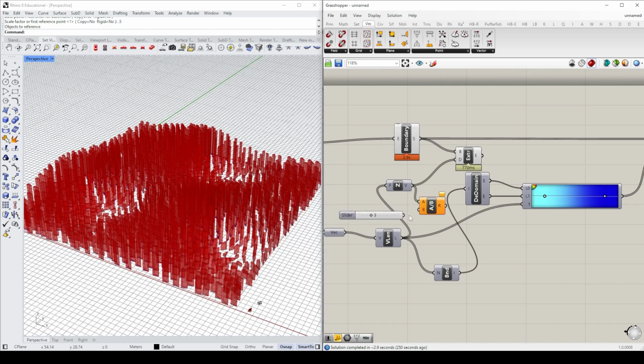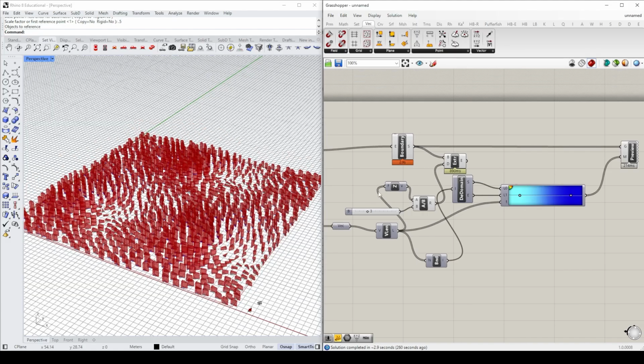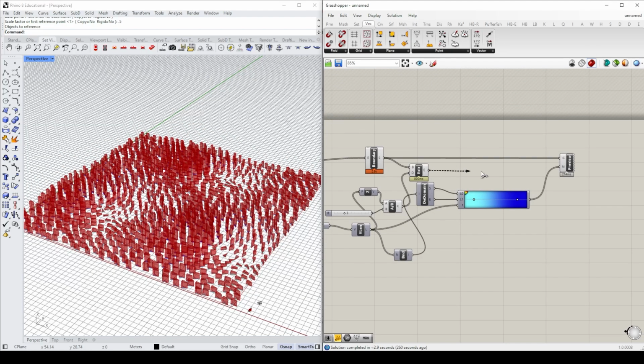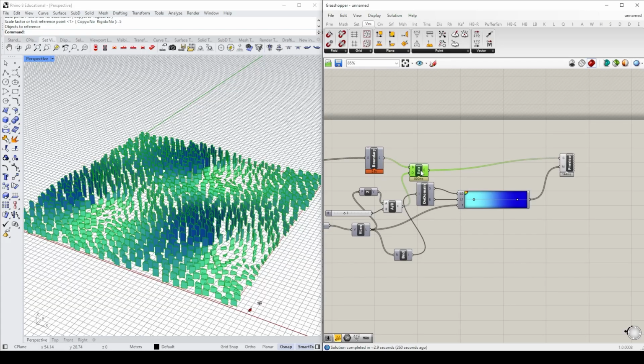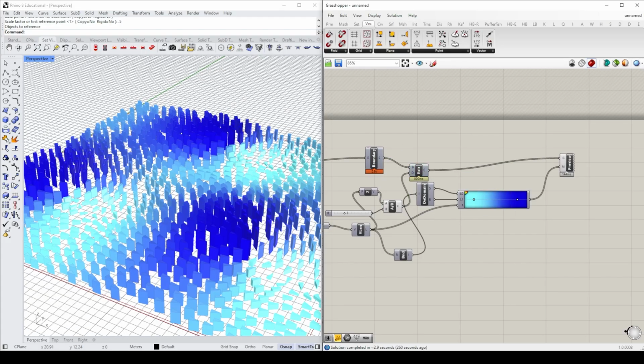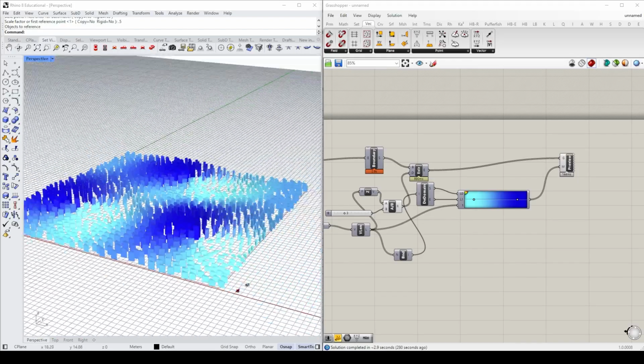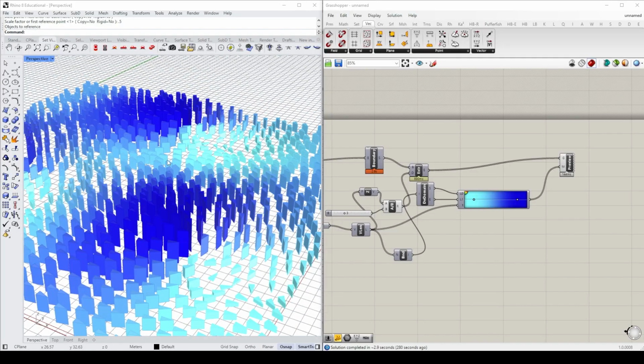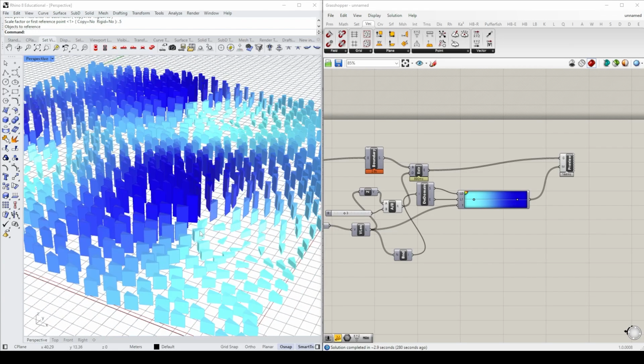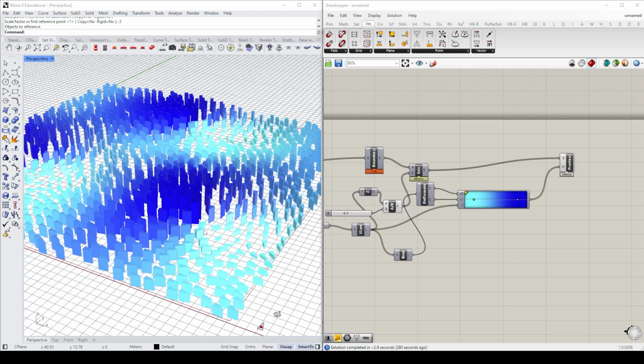Just divide it by the number 3. I think that'll give us good results. And then we'll use that for our custom preview instead. Turn the preview for that off, the preview for that off. So now I have a series of triangles which are extruded based on the vector length, but they are also colored based on the vector length or that amplitude.